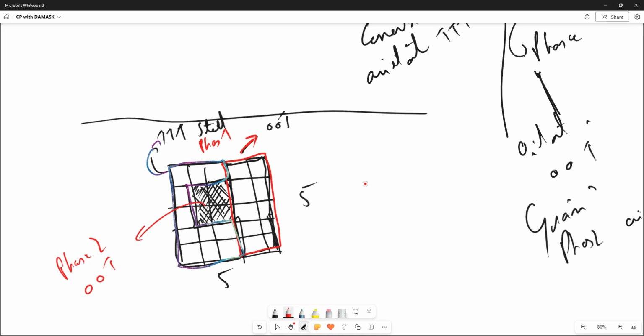From my point of view, when you define two phases in a single system, we need to define the volume percentage. While giving the volume fraction, obviously the data will be in the geometry file, which gives information like where exactly the different phases are located. But we already know where the phase will be. We just want to explain this to the computer.